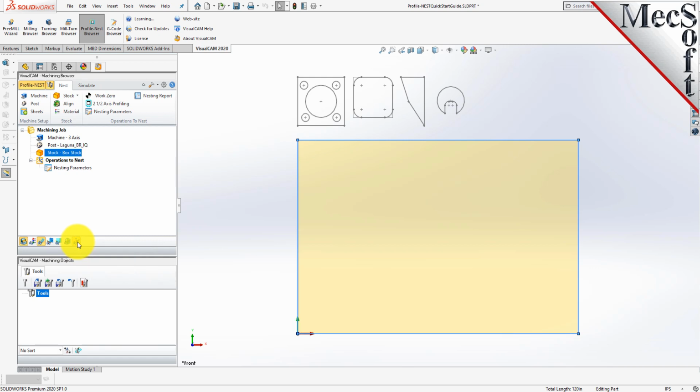So that serves as the origin for the toolpath coordinates if you don't create a work 0. You can, at this point, create a work 0 and put it anywhere you want, and that'll serve as the origin. So we'll just ignore the work 0 for now. We're ready to create our profiling toolpaths. We're going to create our first profile and do our first part.